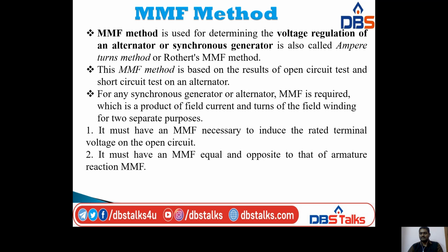In the previous method, the EMF method, we also conducted the open circuit and short circuit tests. Here also, I am going to perform the open circuit test and short circuit test on an alternator. For any synchronous generator or alternator, MMF is required, which is a product of field current and turns of the field winding, for two separate purposes.